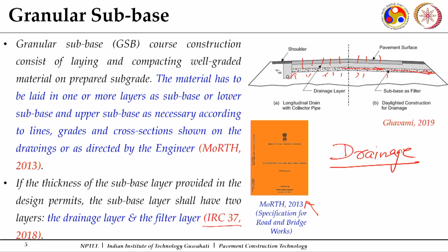And here you can see I have extended this particular layer, and I have provided this drain at the edges of my pavement structure, or it can be extended up to the edges so that water goes out of it and gets collected in your side drains. In both cases, we can see that this particular layer is specially designed.